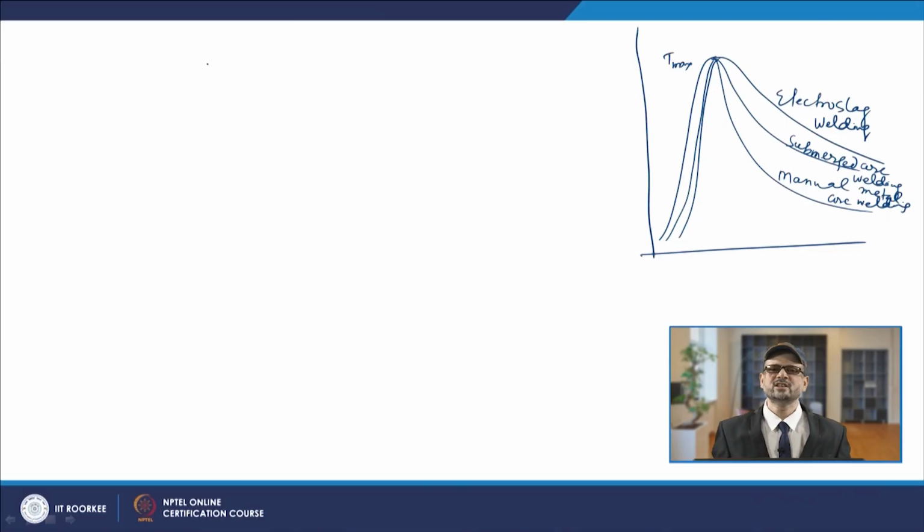So, accordingly you will have its effect on the properties of the material. Cooling rate will be changed. When you have a thicker material, you will have a different cooling rate, a higher cooling rate, and that cooling rate we can further superimpose on the TTT curve that we will see, and then we can predict what will be the transformation products in the case of welding.